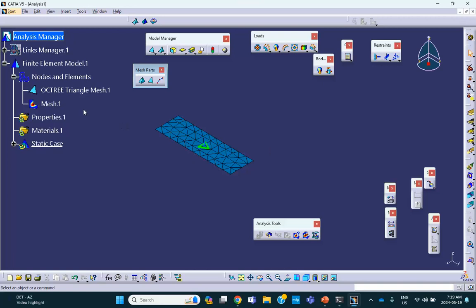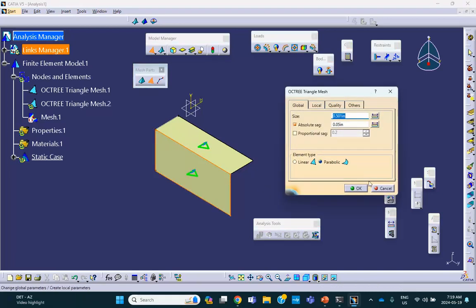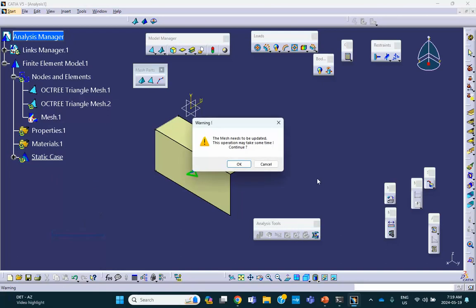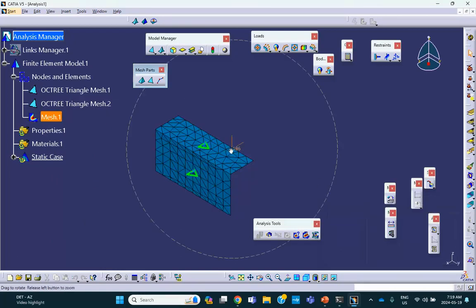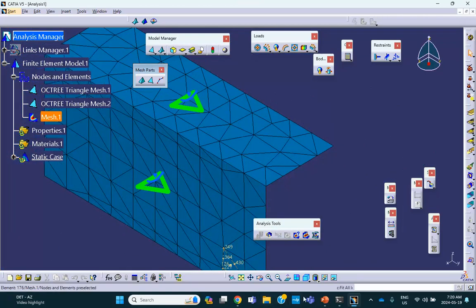So deactivate that. And then again, another one down here. Fine. Show it to me. It'll show both. But look, if you put the cursor at this element from the bottom, you get a bunch of node numbers, 213, 214. And on this side, you get 11, 12, etc. That's why they don't talk to each other. When you try to run, it says, hey, I don't see you, and it's going to bomb. So that's pretty much it, folks.